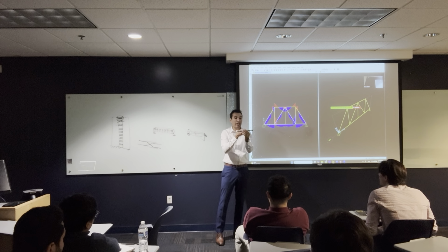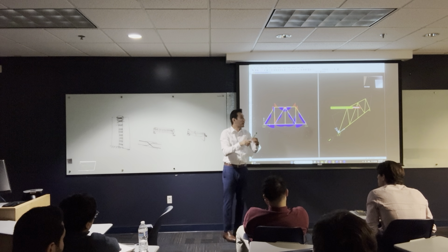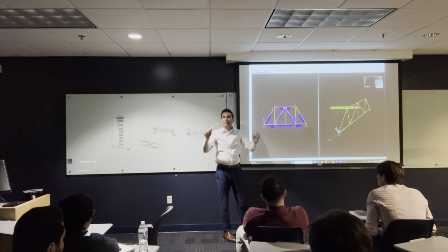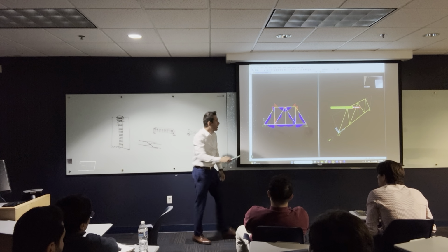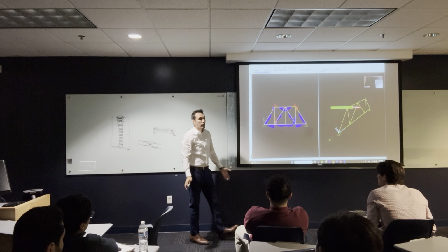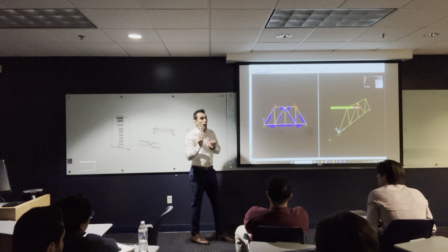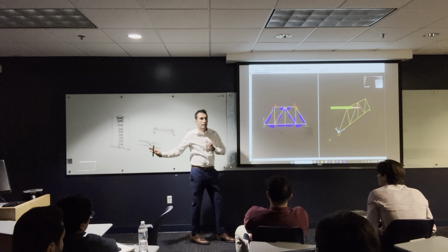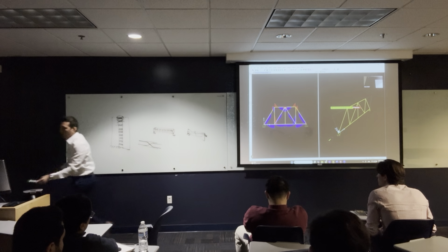The thing is, when we draw this truss, these members were connected to each other, like each connection here was like this. We either move together or be together. So I have to define a special joint here to tell the truss, hey, each joint has a moment equal to 0. We didn't do that. We kept all of them continuous and connected. So we need to tell SAP 2000, hey, all the points here have 0 bending moment. We didn't do that. So that's one way to do it. And by the way, let's keep this for the end because once we finish this, we are gonna still have more errors. So I'm gonna tell you where these errors come from.